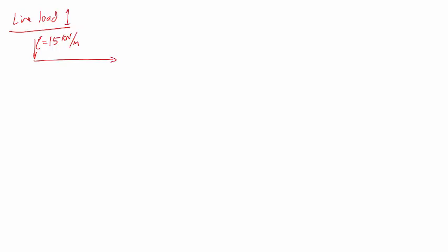And we know that along the x-axis here, we are at 2 meters from that location, and along the z-axis we are 1.5 meters down to get to point A. Okay, and so we want to determine what the change in vertical stress is at point A due to this line load 1. So I'll just put a 1 there.